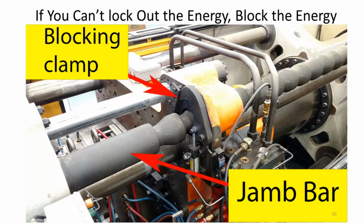Here we're looking at a 1,000-ton injection molding machine that has a blocking device that automatically places itself into a blocking position just prior to the access door opening. In this photo, we're calling it the blocking clamp. In the video that will follow, you'll see how the blocking clamp drops into position on the jam bar just before the operator opens the door. With the blocking clamp in that position on the jam bar, the big cylinder can't accidentally close the mold as long as the access door is open. This is a good example of safety features built into a machine that automatically protect operators from injury. They provide what we call safety coverage.